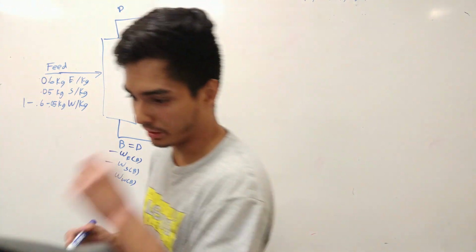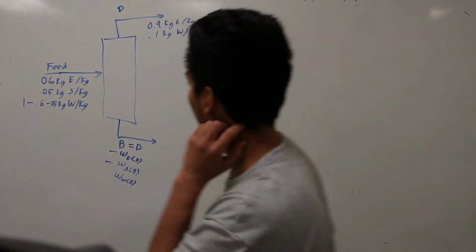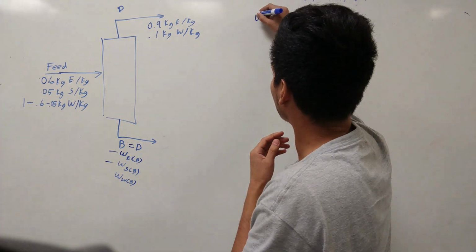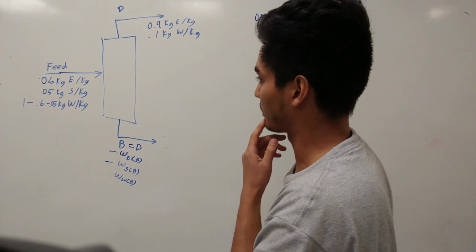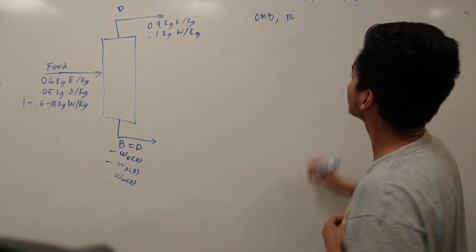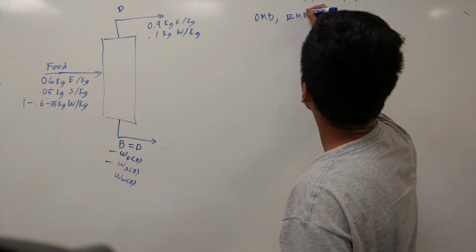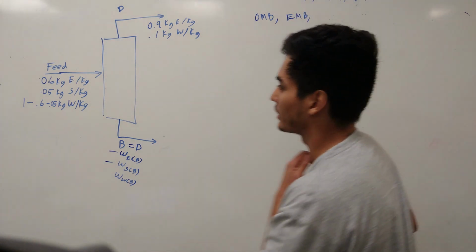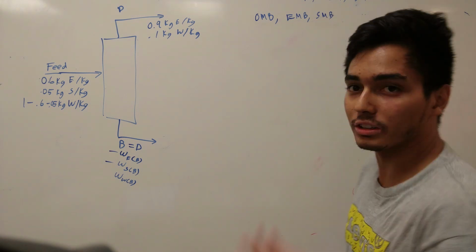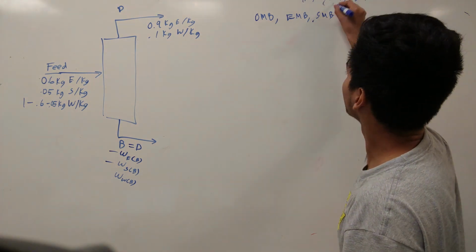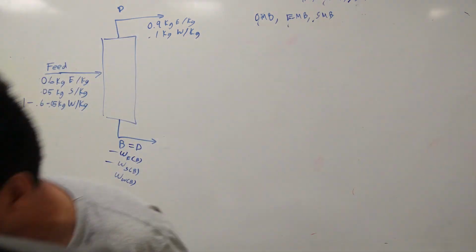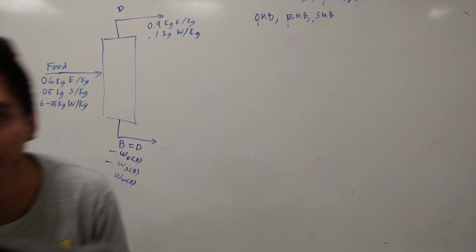All right, and so what do we have for the equations? Well, we got the overall mass balance, and we got the ethanol balance, the ethanol mass balance. Careful with that ethanol. And we got the solute mass balance. Great. Oh, looky here. 3 equations, 3 unknowns. So that means the degree of freedom is 0. Great. Part B.